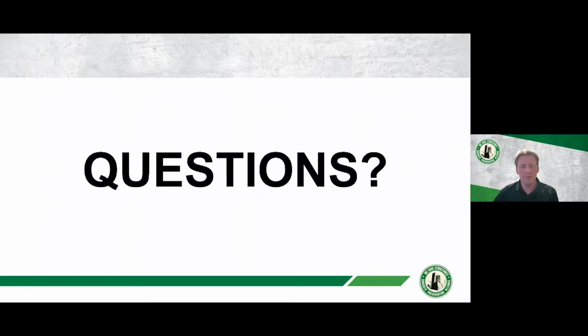Okay, actually, maybe this is a good follow-up question from Sarah. She had submitted two back-to-back. The impressed current systems seem complicated. When would you use an impressed current system over a galvanic solution when it comes to this metallizing, like the Yaquina Bay job versus the, say, Garden City project that you showed us? Great question. So, impressed current systems, they are a bit complicated. The technology has advanced quite a bit over the last, I mean, even 5-10 years.